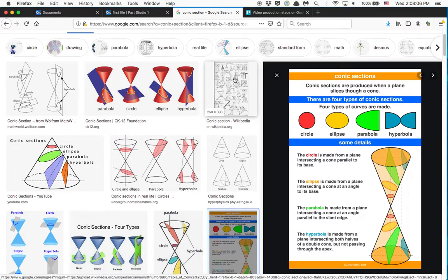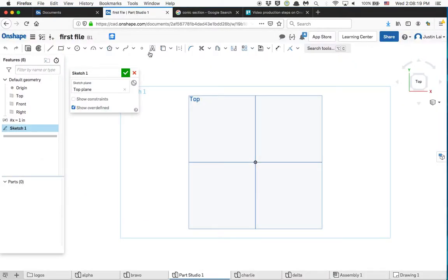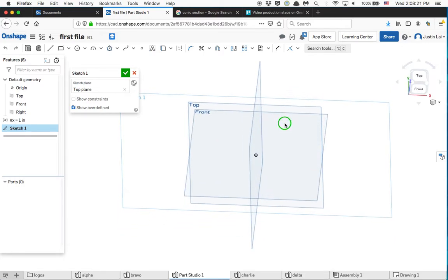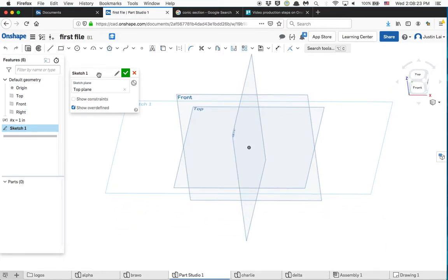And so let's just think about cones. So pause right now. How would you define what the shape of a cone is like? And furthermore, how would you make it in Onshape? All right, you've had a moment to think about it. I can think of 2 ways. And the first way I'm going to do it is I'm going to actually jump to something a bit more complicated. I'm going to say it's a loft between a circle and a point.